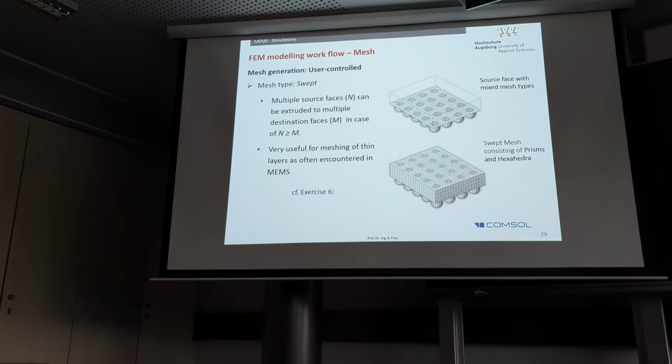If you're interested in simulating that, you would have to simulate a regular array type of structure, and then also swept mesh might be important for the situation of having an array. Probably you guess you don't have to mesh all of them individually. You would mesh one and then you just transfer the mesh to the array function.